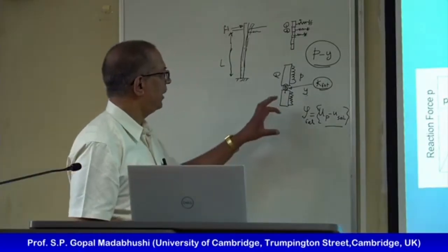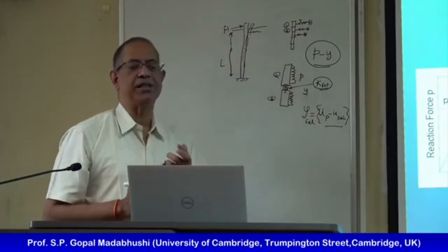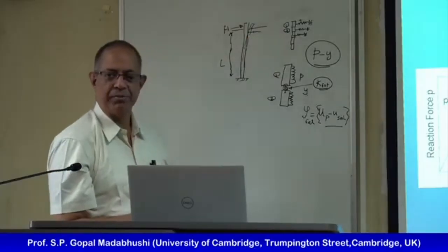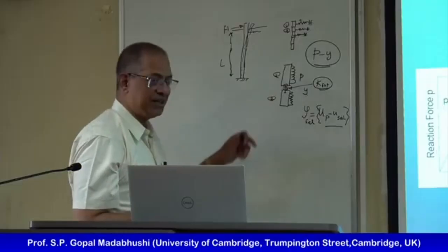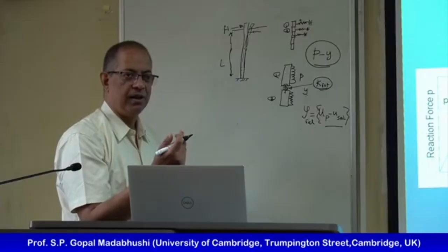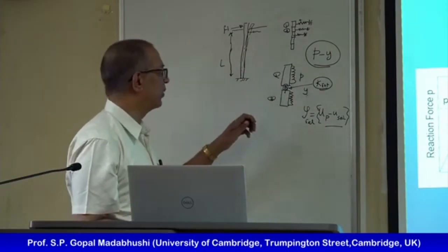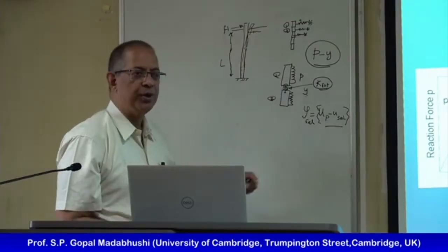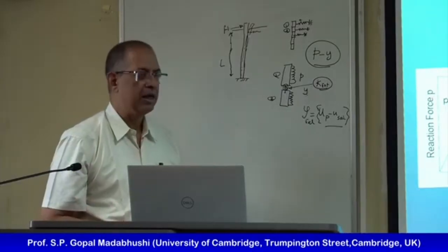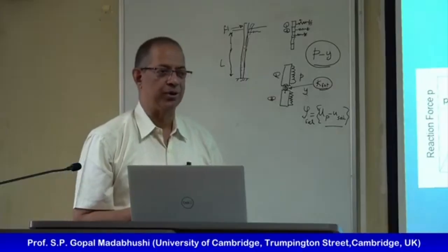So what will happen as I go down towards the base? My relative deflection will get smaller and smaller, clearly, because it's trying to bend like a cantilever, right? But the pressure I get will be getting bigger and bigger. Understood? And the overall bending moment in the pile depends on the interaction between these two. Which is big, which is small, and therefore we get different bending distributions. So this is the famous PY analysis, nothing more than that.